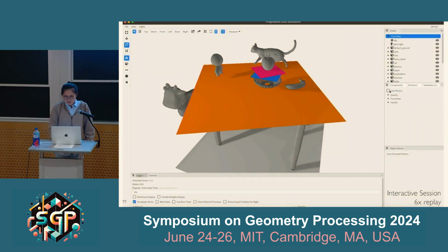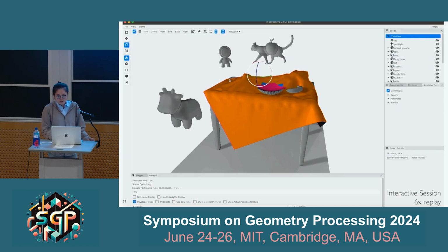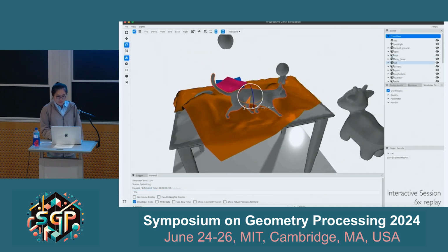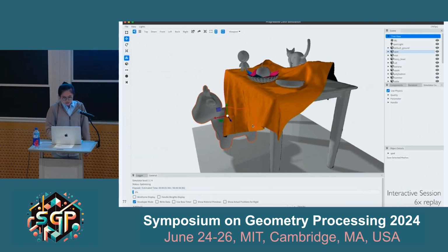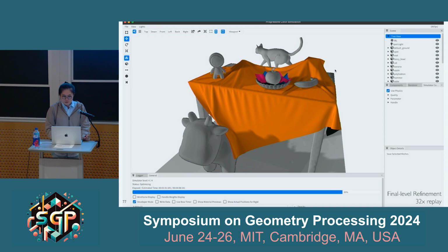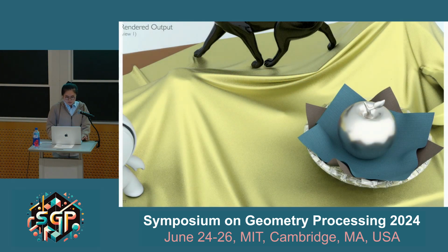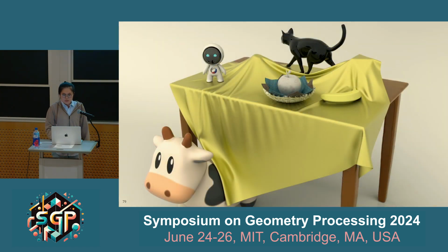And this is a still life example where the user is trying to set up a tablecloth. You can see with PCS robust collision processing, users can directly apply transformations to the complex collision objects to intuitively push cloth around and also between those different shapes. As equilibrium is reached for edits, PCS automatically starts the progressive simulation to finer level solutions. And when no further edits are desired, the user could go grab a coffee and a couple of minutes later come back for this converged, high quality, non-intersecting result for the tightly nested and complex geometries.